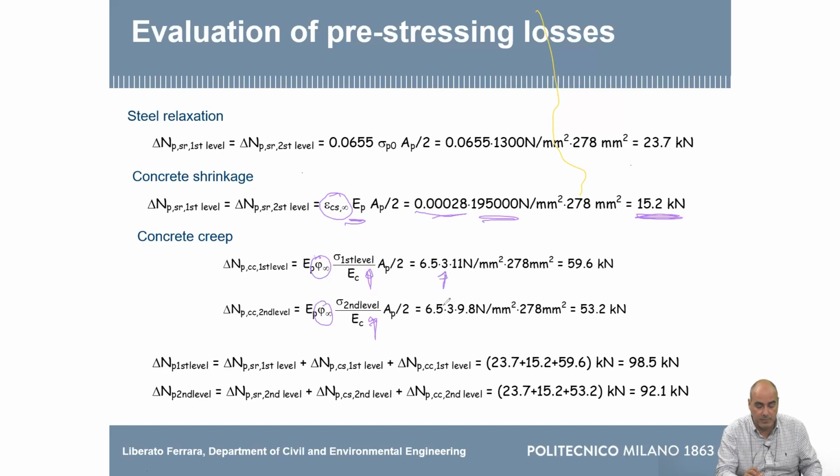We have assumed here, well, it's generally between 2 and 3.5. We have used a 3 here for this type of concrete. So the creep strain can be 3 times as much, twice as much, or something like that, as the elastic strain. So is the process clear? Calculate the stress in concrete.